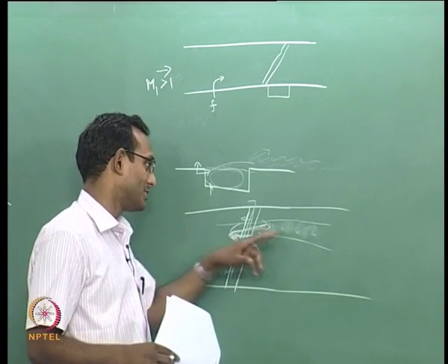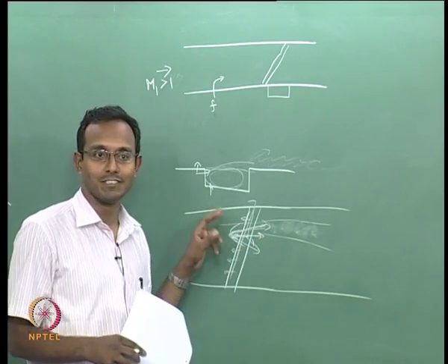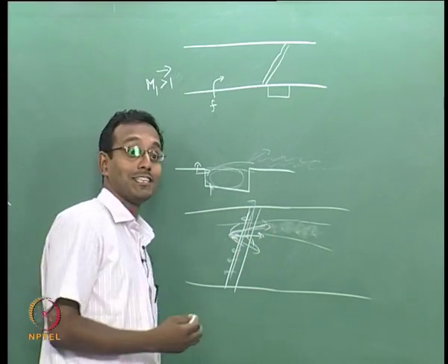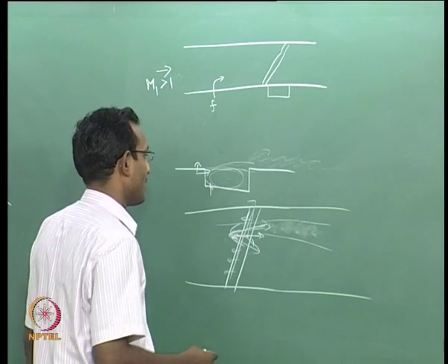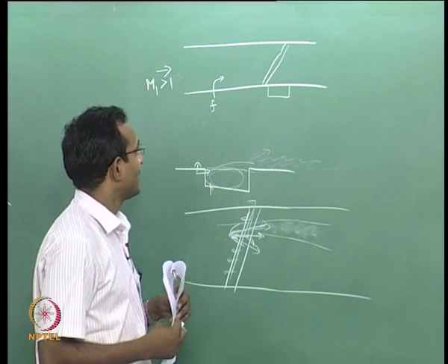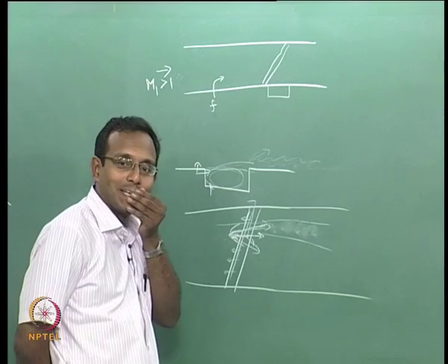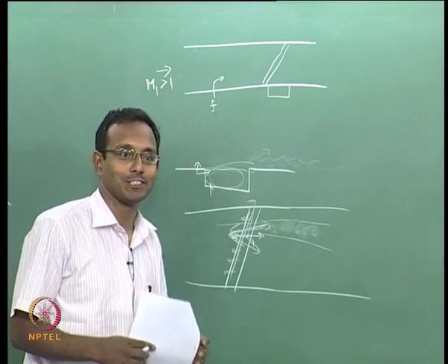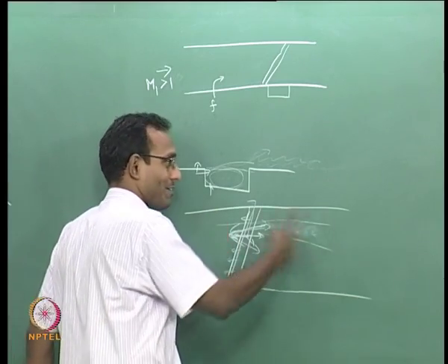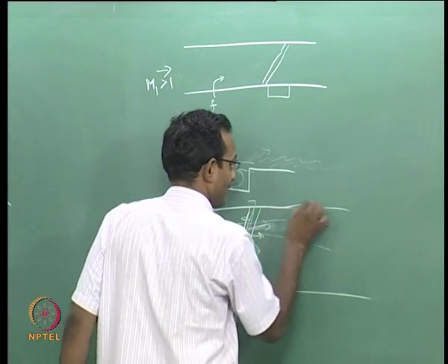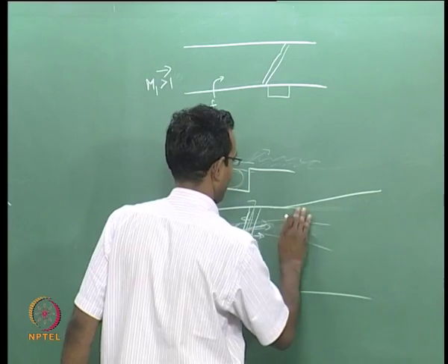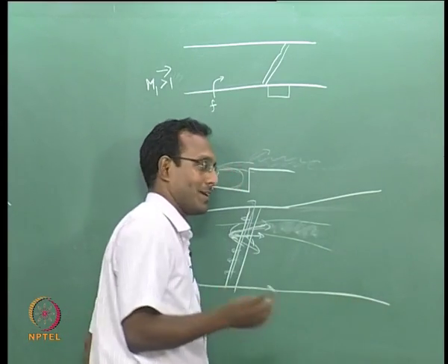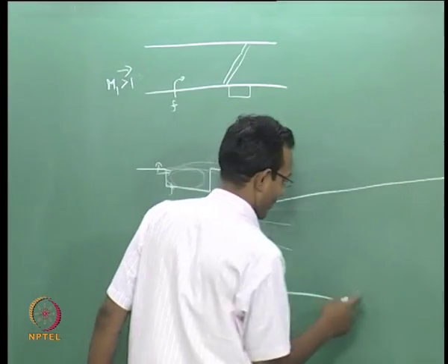Now this is thermal choking; the other things were P naught decrease, so it is typically friction choking or mixing based choking or mass addition based choking. So what are the ideas people use to decrease the problems? They will typically use area expansion. They never have a constant area duct, they will have area increasing, or sometimes they will have a semi nozzle.